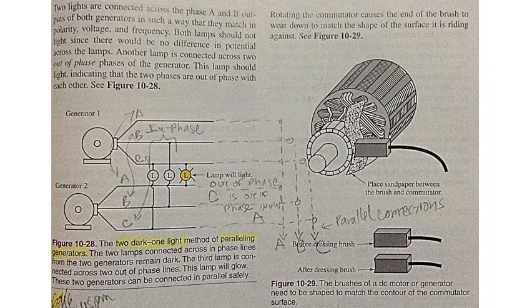Lesson on safety. Before connecting the separate DC power supply to the field windings, the armature leads must be disconnected to prevent the generator from rotating. When voltage is applied to a generator, it will revolve as a motor.